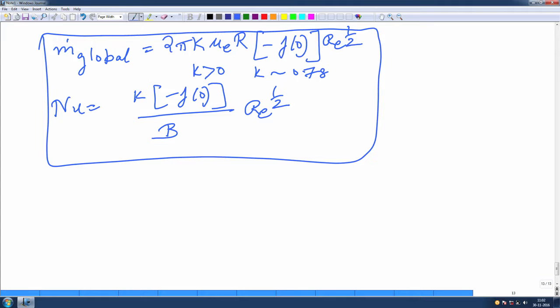Okay. So, this is how we have solved it. Just doing a bit of a recap, we divided the droplet into several pieces, right, and we considered the stagnation flow and the flat plate boundary layer. So, you use the similarity transformation to basically link the velocity and other things, and there we established 3 boundary conditions. The last boundary condition comes from the energy and the species combining it, and we have not shown the math of how exactly the steps go. We have devised that there are 2 quantities of importance. One is the Nusselt number, which is for the heat transfer coefficient, and the other one is basically the global evaporation rate. Both are solved in terms of this similarity variable or the Blasius solution, right.